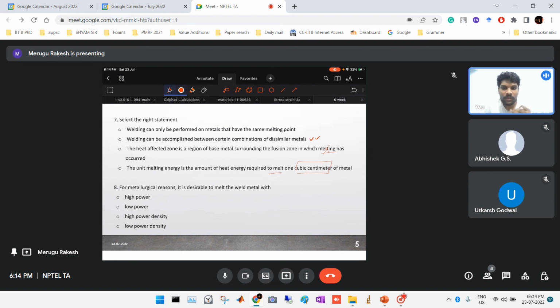I will give some small examples. For example, for high power density, I can say laser welding, in which we have very highly concentrated energy within a small area. In such a way we avoid the heat affected zone and perform very neat and clean joining of two metal plates or something else. It is not always true, because the gap should be within a certain range to perform this. If the gap is too broad, we cannot perform it every time.